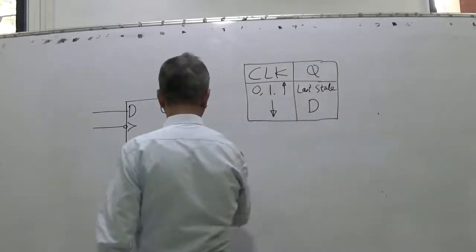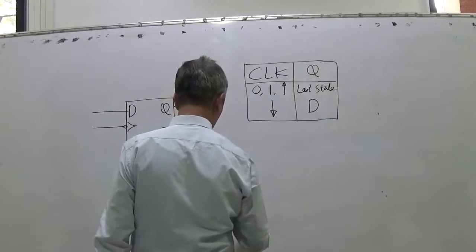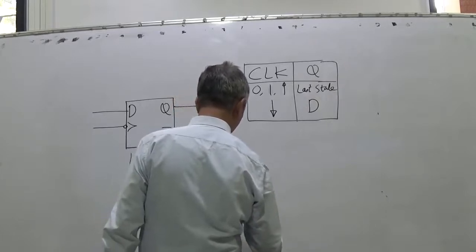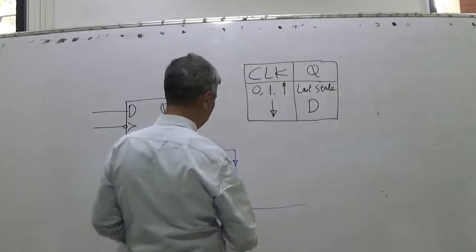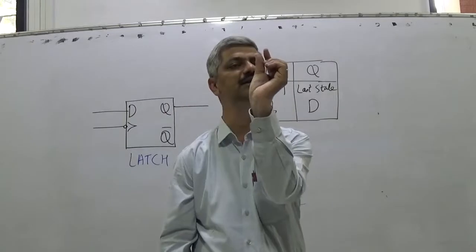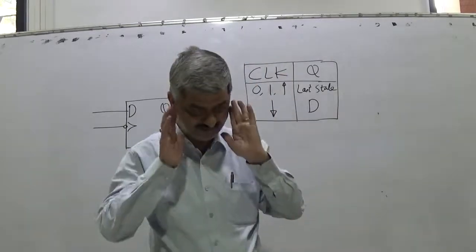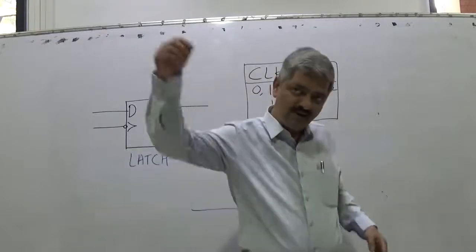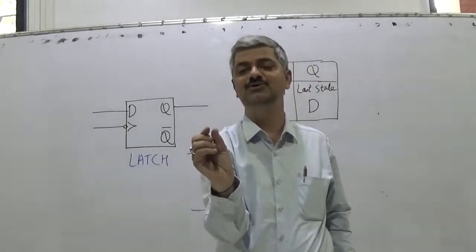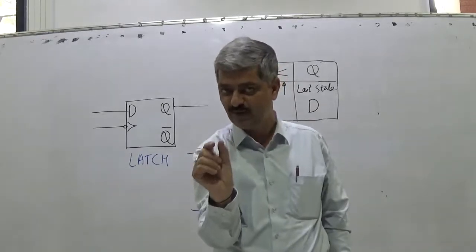When the clock goes down, for a small period, infinitesimally small, a few microseconds, this is a broad discussion I am telling for understanding. Whenever the clock goes down, immediately at the falling edge of the clock, we get a 10 nanosecond period in which the enable input of the internal D flip-flop becomes 1.